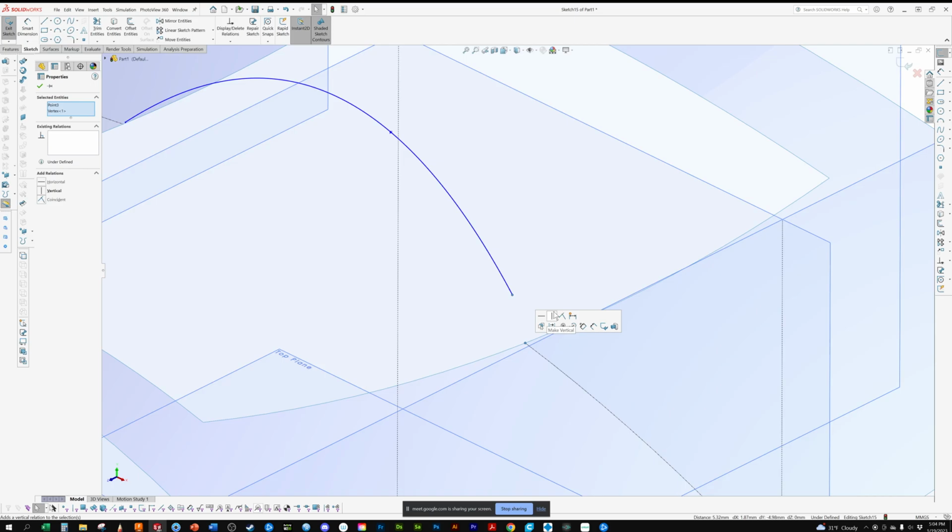So exact same thing. Instead of doing a lofted surface, I want even more control. So I had the original control, but now I need better control right here in this very localized area. So I'm doing patch surface modeling. I'm cutting out a patch and then I'm filling it in with the surface that I want. So I'm going to come in here, and now I'm going to use my boundary surface because I've got a defined boundary.